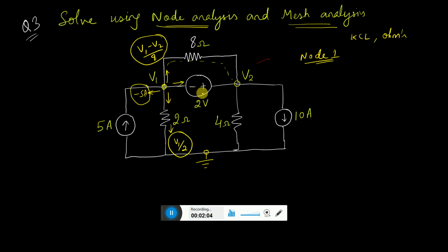But here you do not have any resistance, so how do you find the current over here? There are many ways in which you can solve it using a supernode and other things, but let us go for a simple way. Let us say that the current over here is Ix. So Ix is a current which I do not know, moving in this direction in this wire. That is Ix, a fixed current. As this is a voltage source, for the time being we will just say that this is the current Ix which is moving from node 1 to node 2.